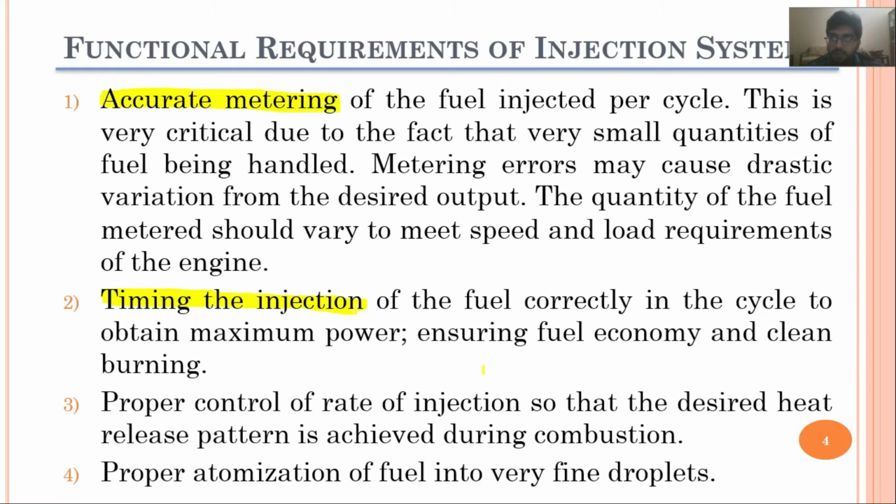It is important due to the fact that if there is some mistiming in the fuel injection, it may result in improper combustion, and it can cause a decrease in the fuel economy, and not only a decrease in fuel economy, but it will also produce some undesirable waste gases as well.